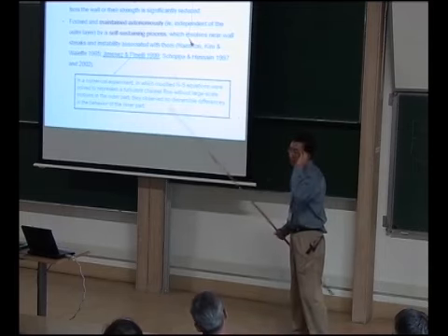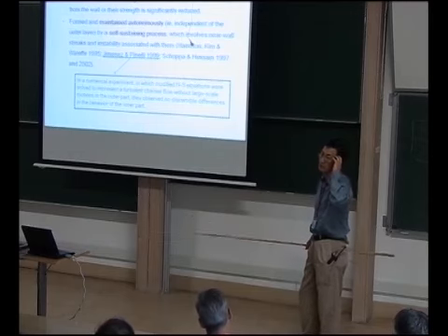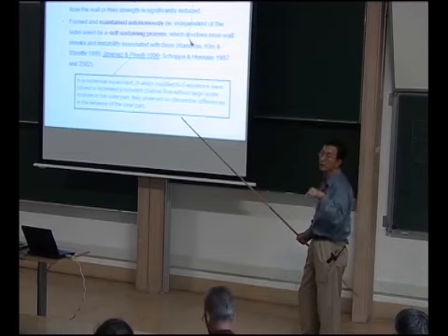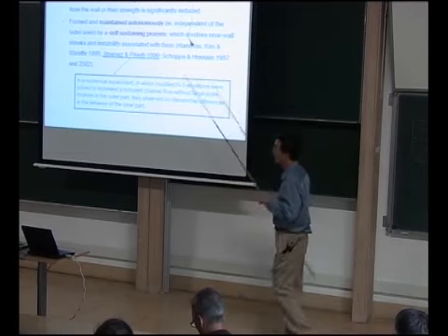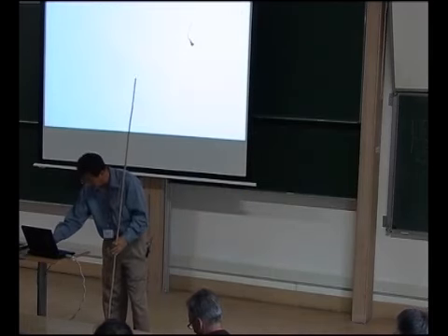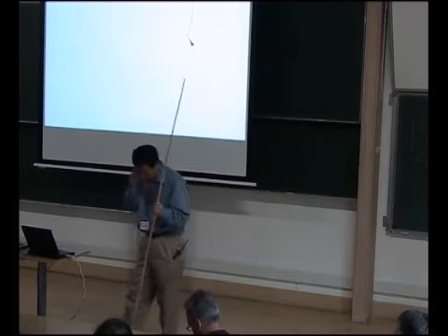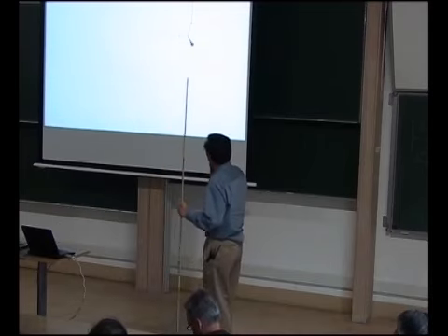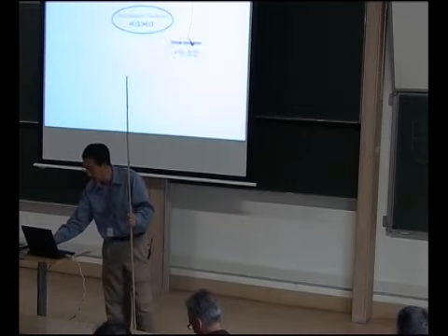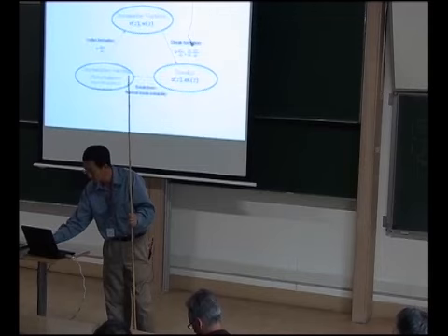They modified the Navier-Stokes equation in such a way that they filtered out some large-scale structures in the outer part, and then saw what happened near the wall. They saw almost no difference between the two, so they concluded that whatever the influence of the outer part is, it's a secondary effect. I think that's a nice example of what a numerical experiment can shed light on.